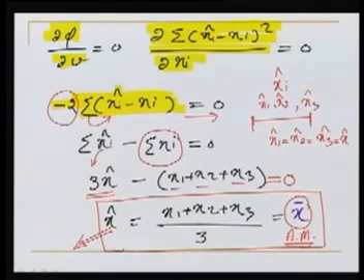So what have we proved here? We started with the concept of the least square. Starting with that concept, we found the residuals. We made the sum of residual square equal to the minimum. And in doing that, we arrive at the conclusion that the best possible estimate that we can achieve for this set of observations by least square is the same as the arithmetic mean.